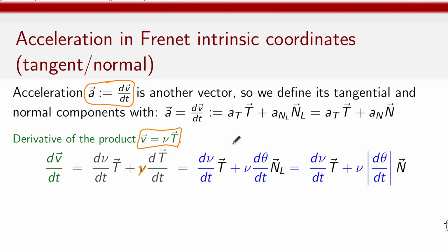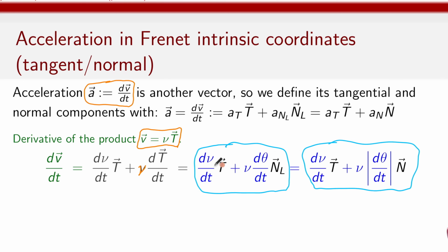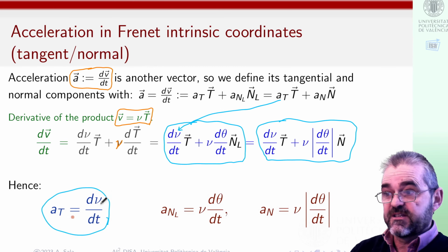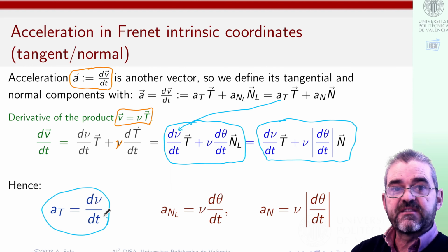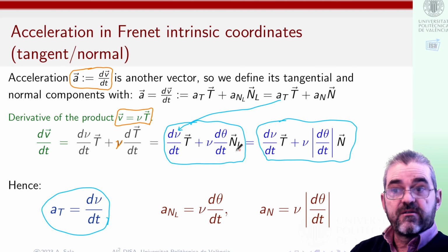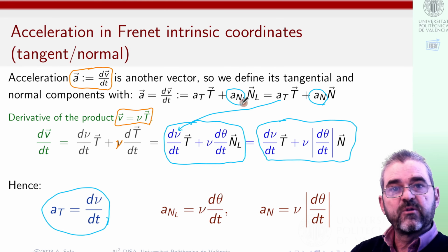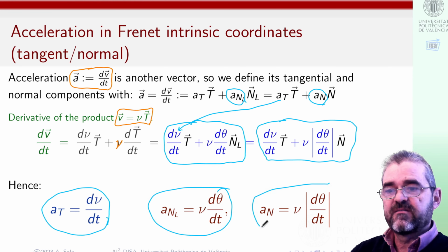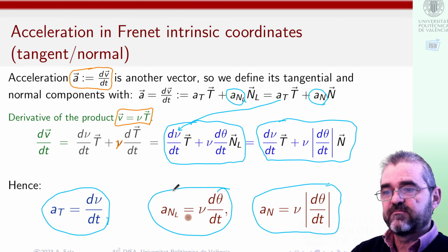At the end, this is the acceleration vector, or this thing, and its component in the tangent direction will be called tangential acceleration. So this is the tangential acceleration, the time derivative of your speedometer reading, and the component in the normal direction will be called normal acceleration, either a signed normal acceleration or an always positive normal acceleration, given by one of those two expressions.